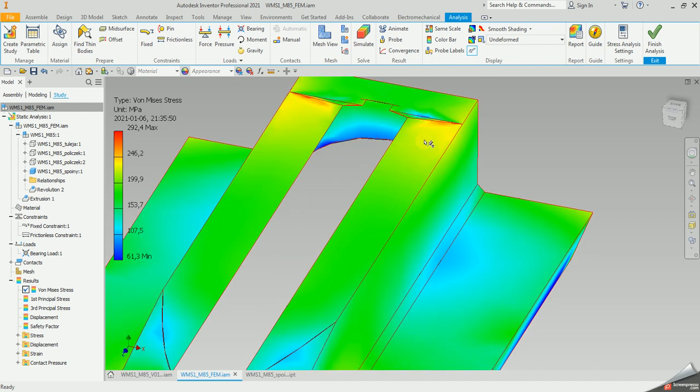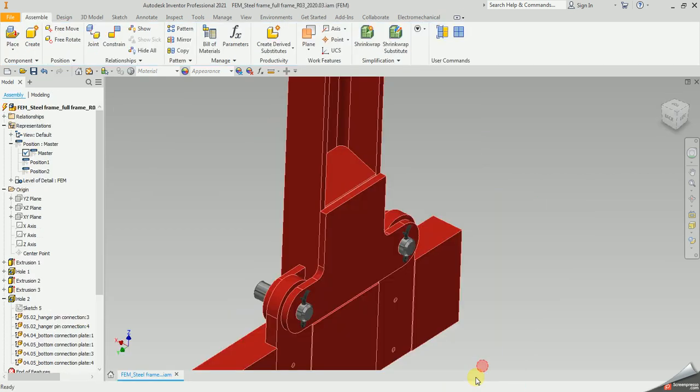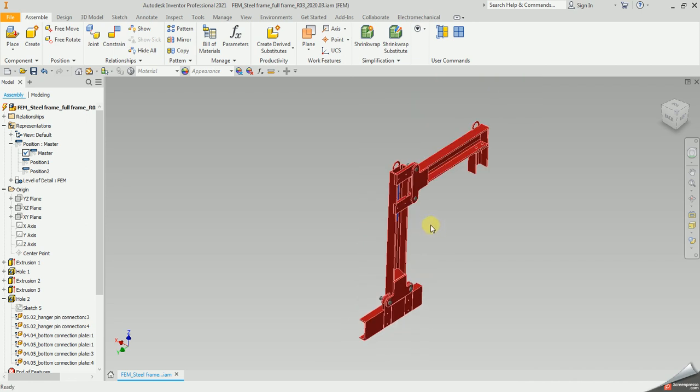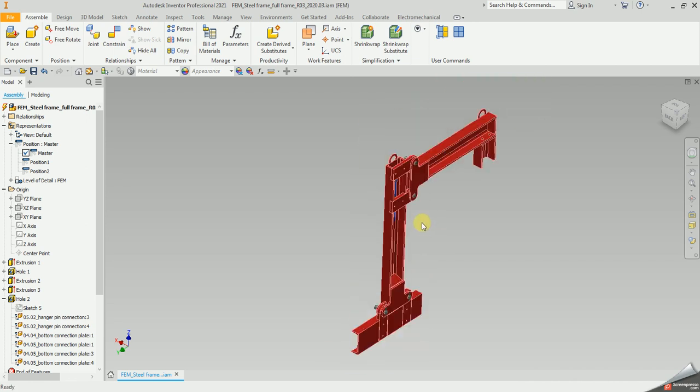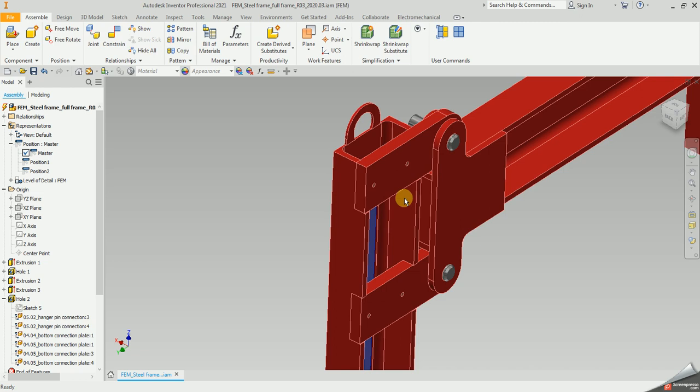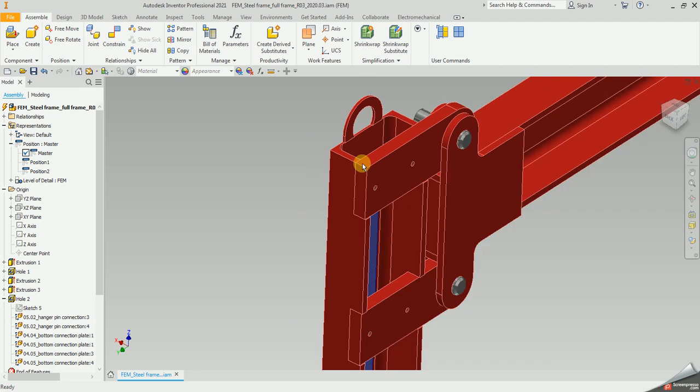So overall, I was trying to look for other assemblies that I used for finite element analysis that would use welds, but really I didn't find much. Even this one that is quite complicated is done without welds, because it's easy enough to assume bonded connections here, and they are close enough for how this will be after it's welded, so there is no point in bothering with modeling welds themselves.